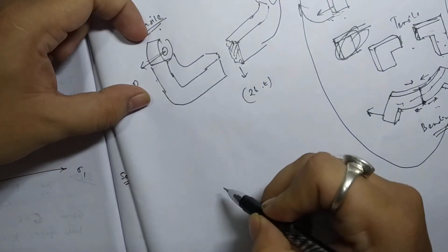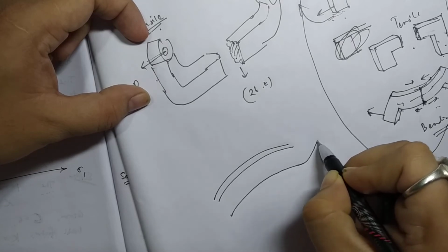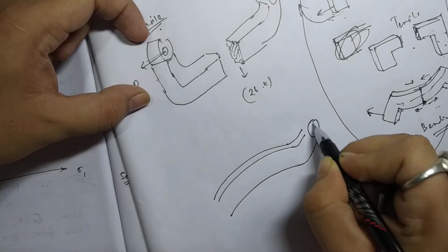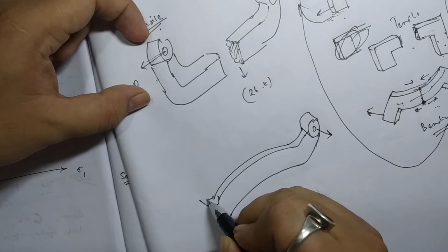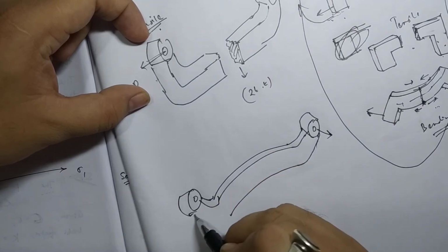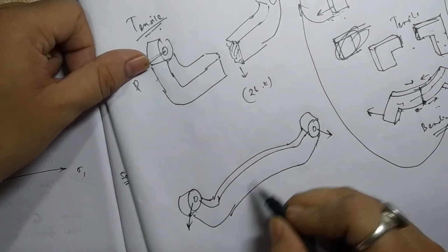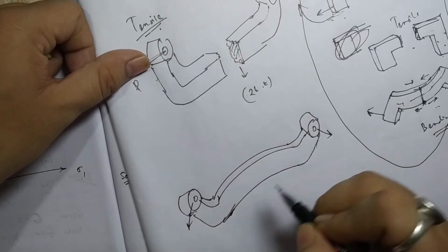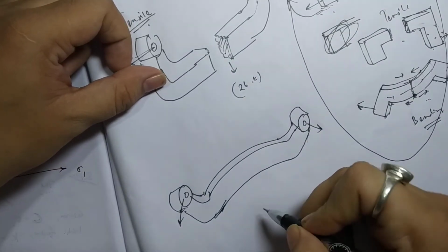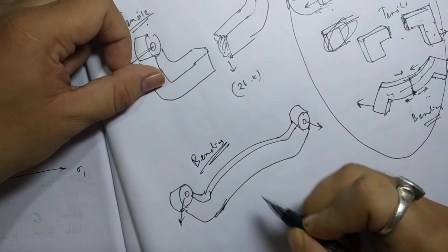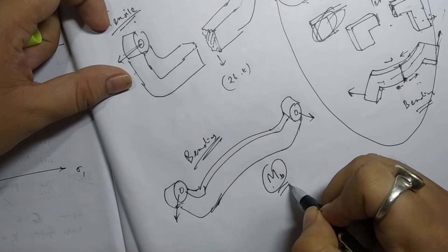Another failure possible is bending. So this is the bending type of failure. Okay, you agree? Because of pulling it like this, some bending will take place. So here we don't take a failure area because it is still bending, it will break somewhere. Rather, we have to find out its bending moment. See, bending is caused by a moment that is called bending moment, MB.